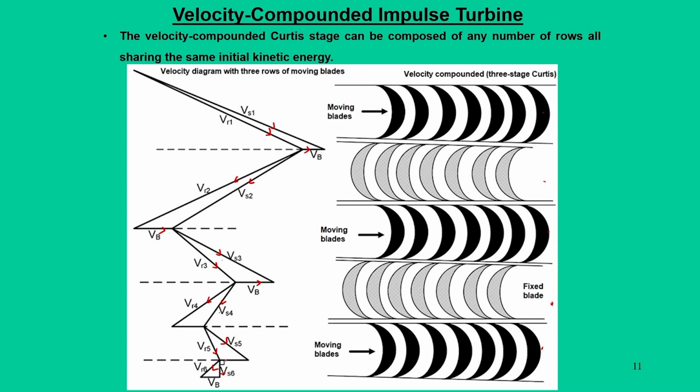So, till how long can we do that? When this velocity which is impinging, now it has, if you see, this magnitude is very less. So, in a realistic way, if you draw the vector diagram appropriately, you can see that the length of this magnitude Vs6 is quite low. That means you have captured maximum energy from the fluid, because its magnitude has reduced substantially. That means, if we have this Vs1 length of value, finally Vs6 becomes an insignificant number.